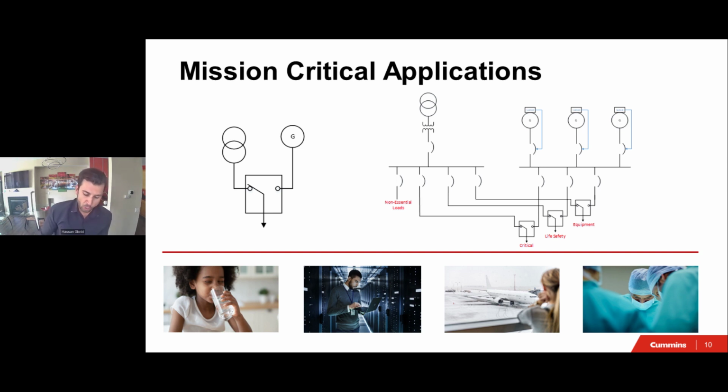By the way, for codes and standards, transfer switches are tested and designed to the highest standard in the industry, UL 1008. And UL 1008 is harmonized with the Canadian standard, CSA, and it's also harmonized with the Mexican standard, ANCE. There are just minor variations, but it is the leading standard for safety for transfer switch equipment.